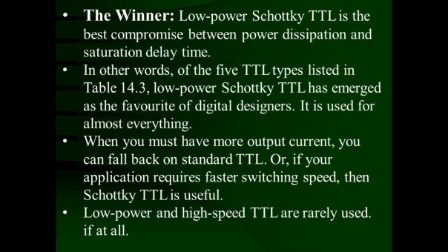Suppose you require higher load currents or higher fan out capability, then you can go to the standard TTL. On the other hand, if you require faster switching speed, then the Schottky TTL 74S00 series is useful. Low power and high speed TTL are rarely used, if at all.